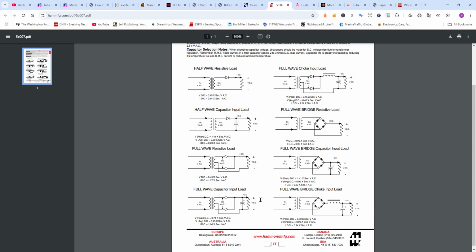And once you kind of get in your head the number 1.4, which is a multiplier for your power, and usually about 1.2 for a rectifier tube, but 1.4 for solid state, then some of this becomes academic. But it's a good thing to have, and again, when you're starting out, it's a great little resource.